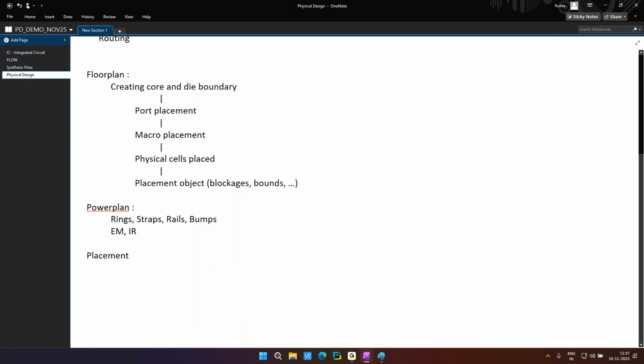Okay. So now when we talk about standard cells, I will have 50,000, 1 lakh, 10 million, 3 million, like that. Each and every cell I can't pull and place, right? The tool will itself take care. Okay, while pulling that standard cell inside the core area, how is it getting pulled? What all optimization techniques is it performing? So here first is coarse placement. We have three major categories: coarse placement, legalized placement, and detail placement.